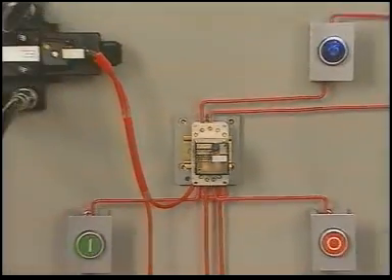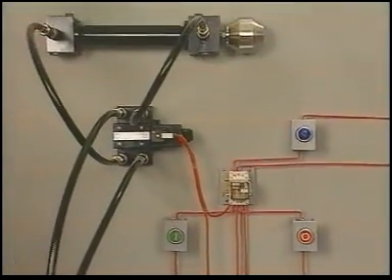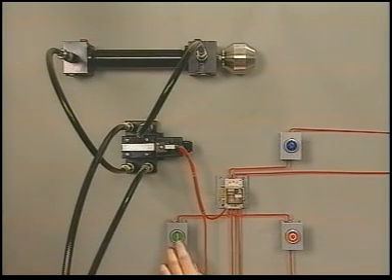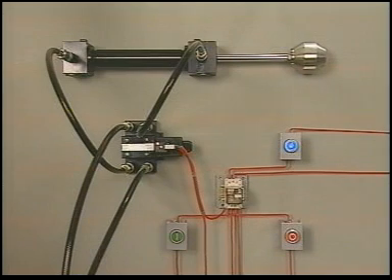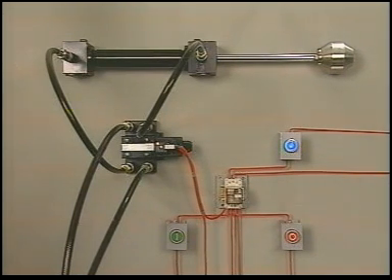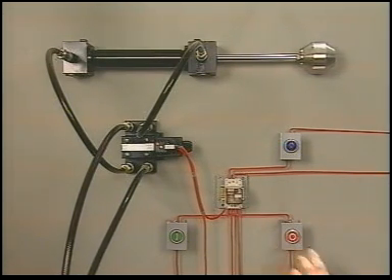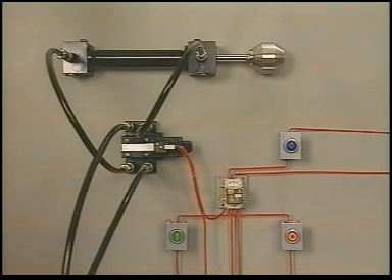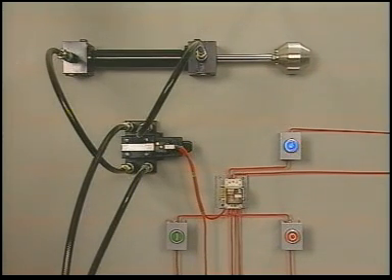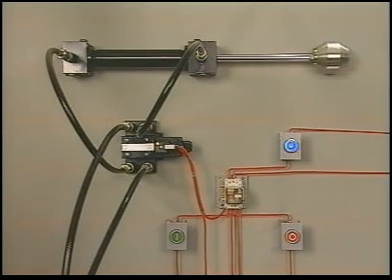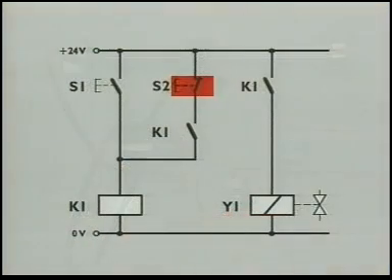Electrical signal latching is needed when spring return valves are used, because in this case the signal must remain present as long as the valve is to remain in the switched position. In addition, the position can be indicated by a signal lamp. This requirement can easily be met with a self-latching relay.